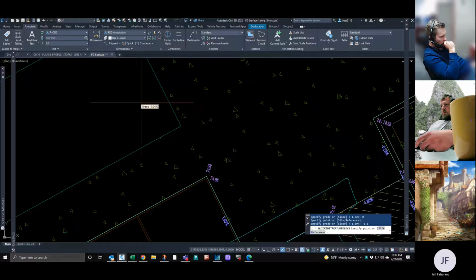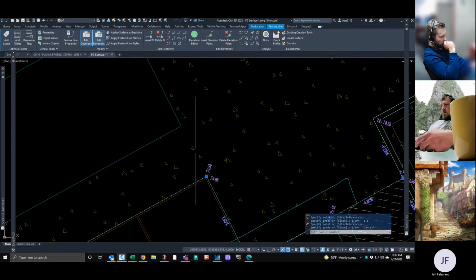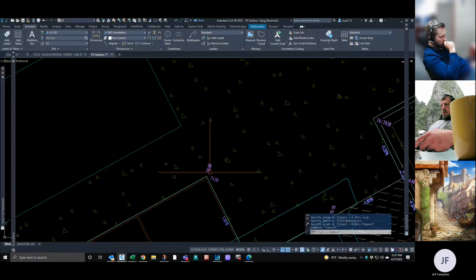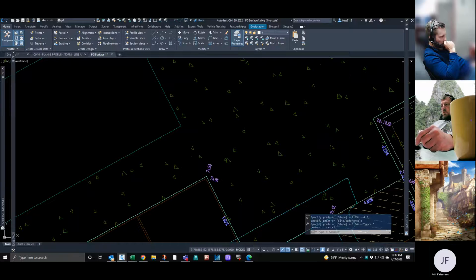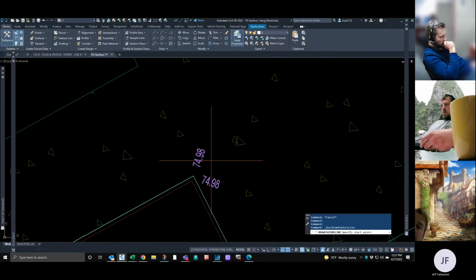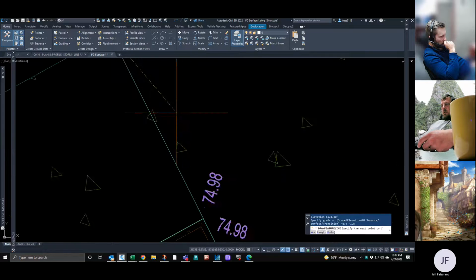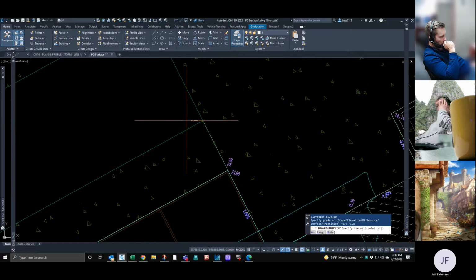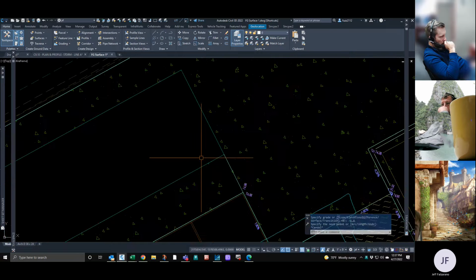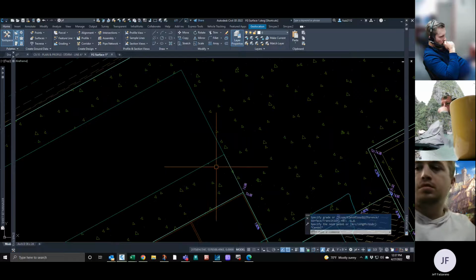And then once you have all these grades in, these elevations set, then you can either do a stepped offset, or in this case, if I need to get a 1.8 to there, I just draw another feature line in. So I go create feature line, go from this endpoint here, and I go from surface, FG surface, go in this direction, and then I set my grade right here at a minus 1.8. And there's your starting point for that part of the sidewalk, and then you can just run a feature line all the way around this.